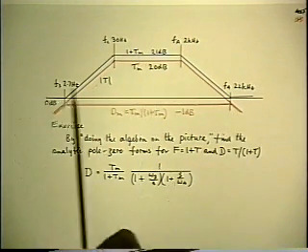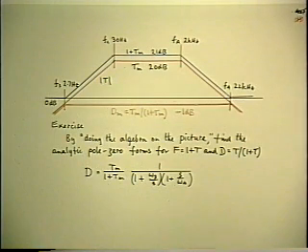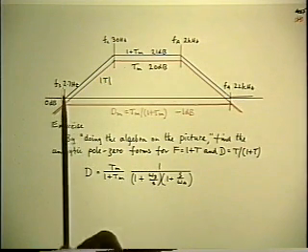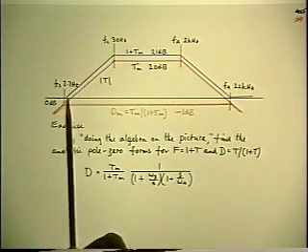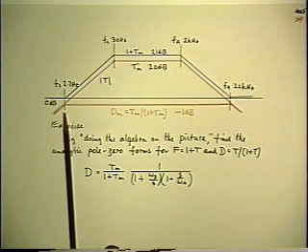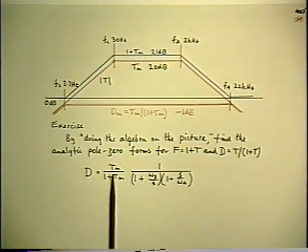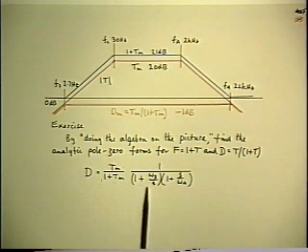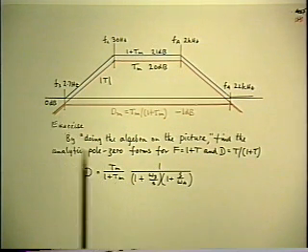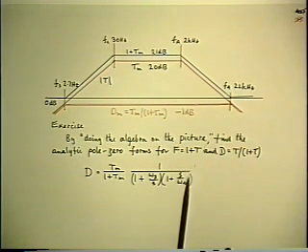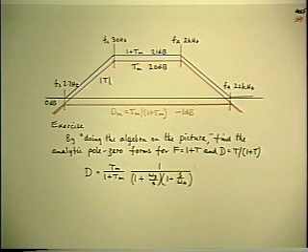And the construction at the bottom end obviously is just the reverse. So d stays flat until you get to the frequency where the blue line levels off, and then d again follows the t downwards. And analytically, d is flat at the midband value, and it has an inverted pole at omega 3 and a normal pole at omega 4, which we've already defined in the previous step.